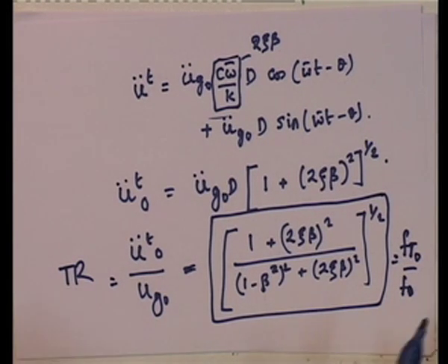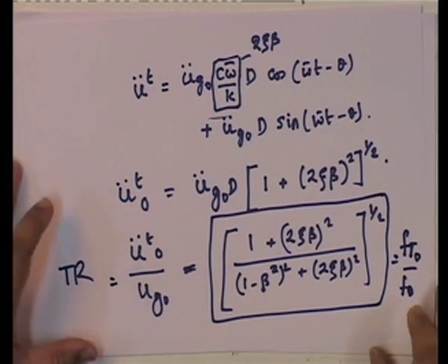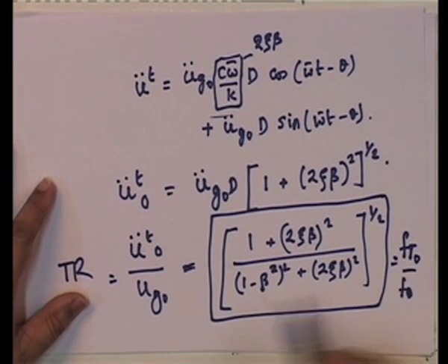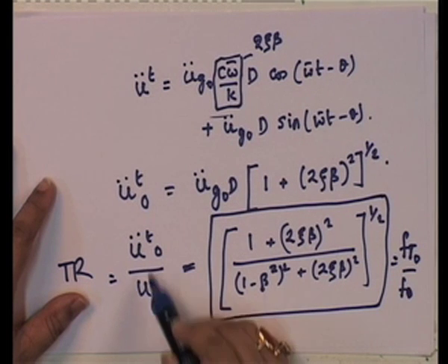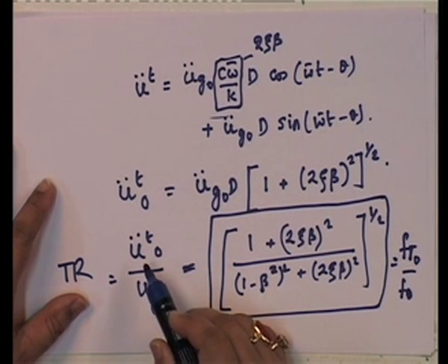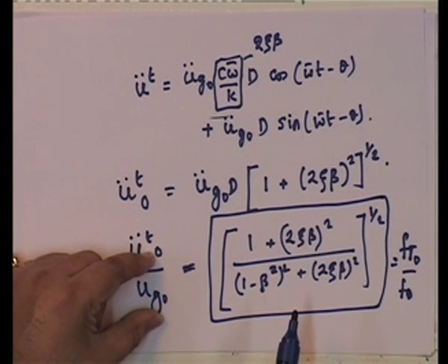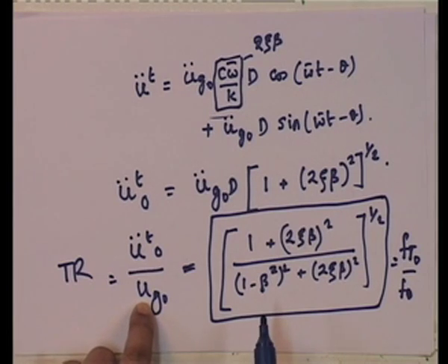Two totally dissimilar problems, absolutely dissimilar problems. One is a force transmissibility problem, the other is transmission of base acceleration to the equipment acceleration. So, this is a base isolation problem. We are trying to isolate the base vibration transferring on to the equipment or whatever, any other, I am calling it equipment for want of anything else.